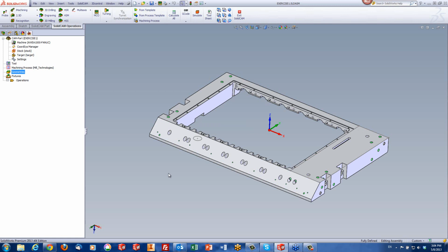If it has a hole on the surface, it won't see it as a hole. It will see it as an area that does not have any kind of surface on it. So in those areas where you have a hole, it just won't machine because it doesn't see it as a hole. It sees it as an area not to be machined. What does it actually do? Well, we'll see that exactly in the program itself.